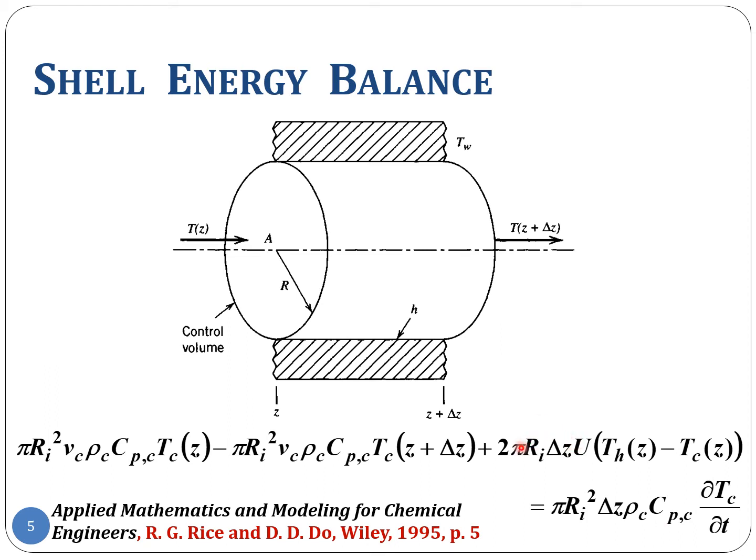Now if you ask yourself, this energy is transferred into the fluid at the radius equal to capital Ri, the subscript i indicating that this is the radius of the inner pipe, right? So this flux will be the heat flux, and this flux of course is equal to minus k dTc/dr, the radial temperature gradient, if you would go from the wall to the center of the inner pipe, right?